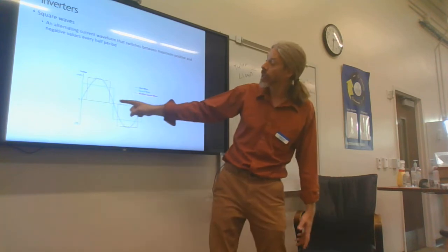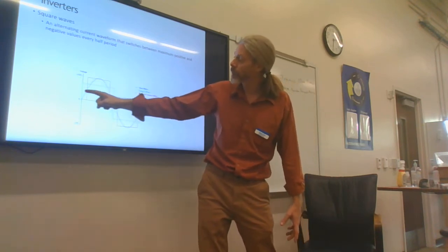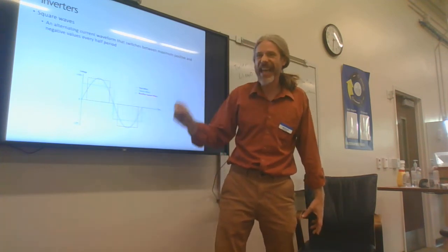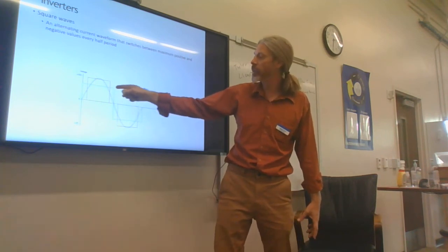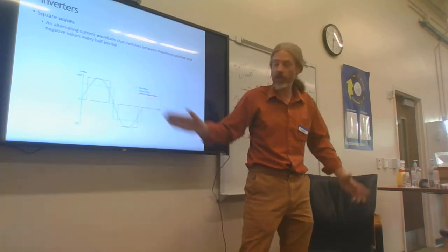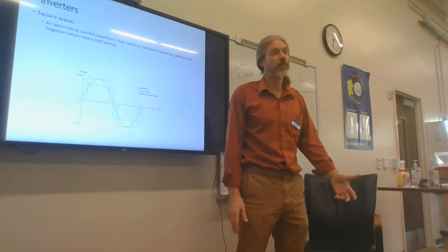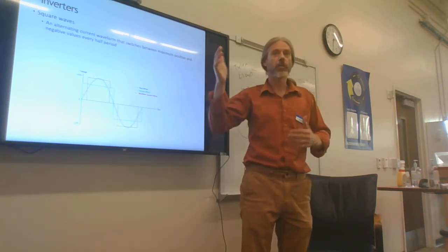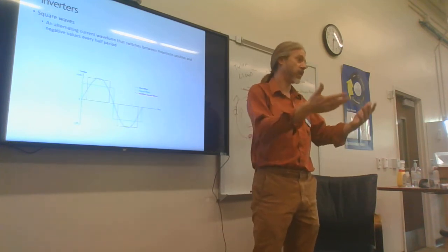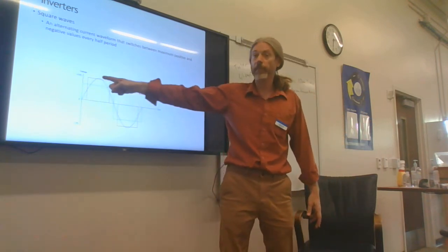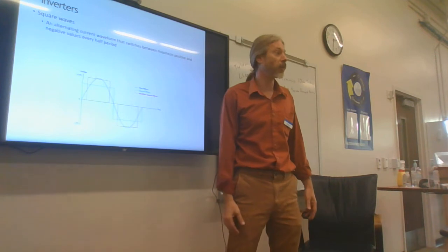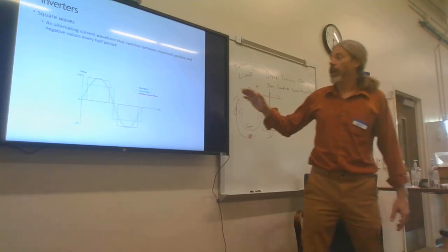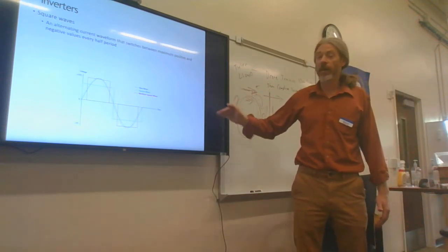Guys, if you did the math, the area underneath this sine wave and the area underneath this modified square wave is exactly equal to the area underneath the sine wave. They all have the same area. That area is representative of the power that they produce. Right? Higher voltage, higher current. Volts times amps equals power. So as my voltage goes up, my current flow would be going up also. All right. Questions over a sine wave, square wave, or a modified square wave?